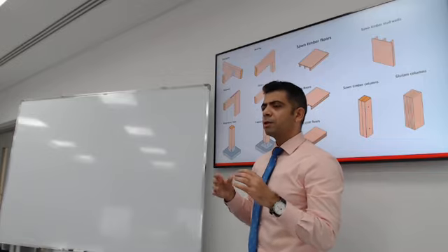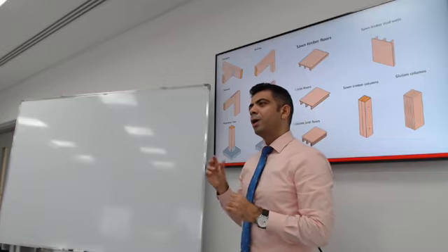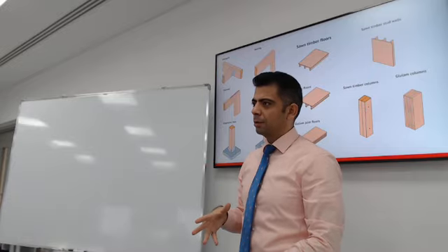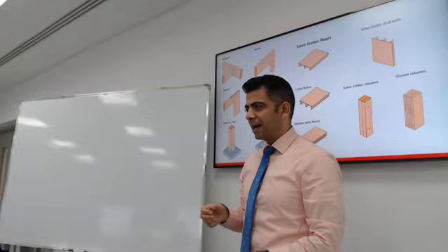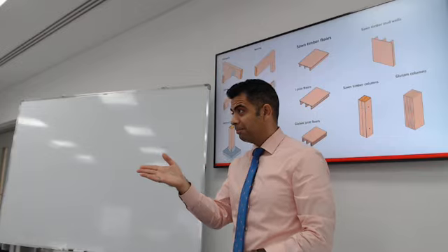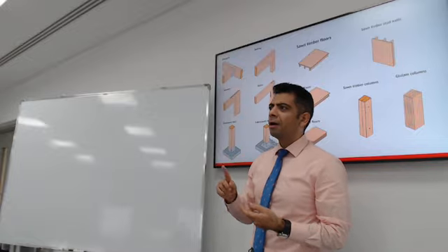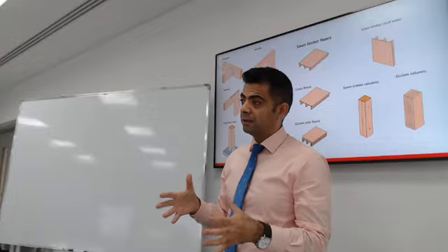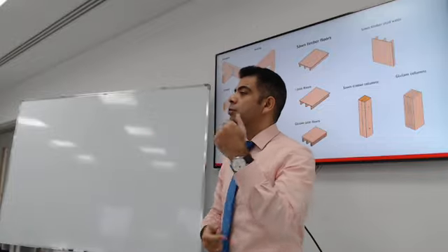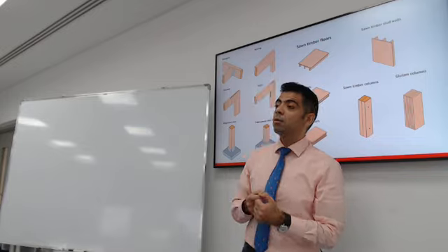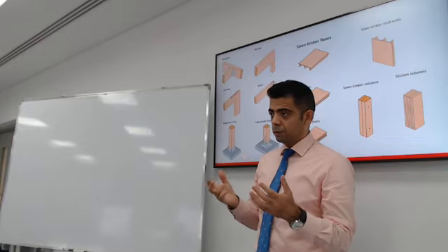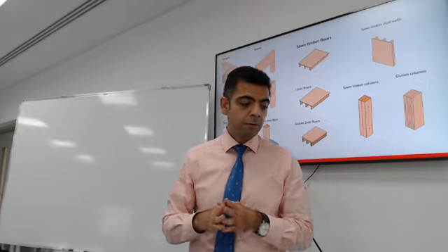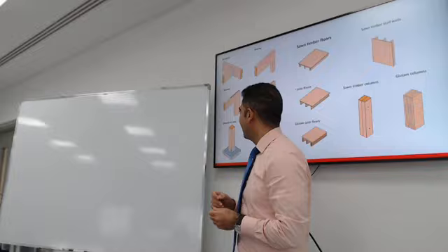So, based on what I said so far, what do you think the relationship is between wood and underground structure elements? Is it a good idea? Why is that? Water. Moisture. If you bury wood unprotected in the soil, with the seasons, with moisture, with the elements, it will deteriorate. In a very short duration, you will have no foundations to be considered. So what do you want to use instead?